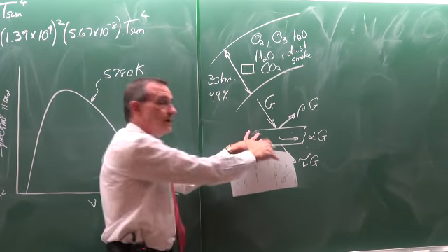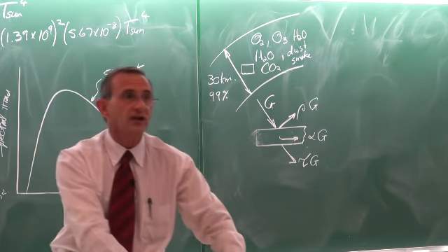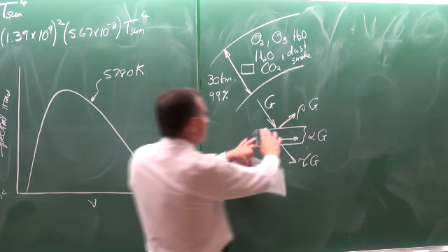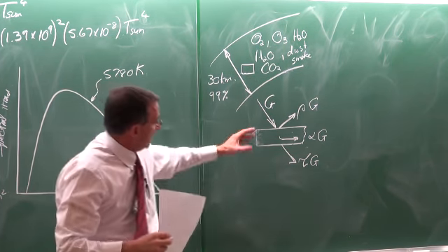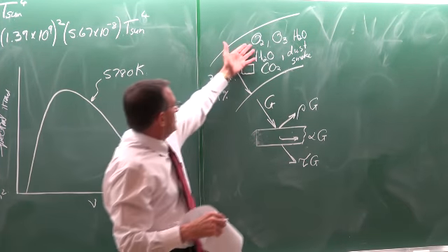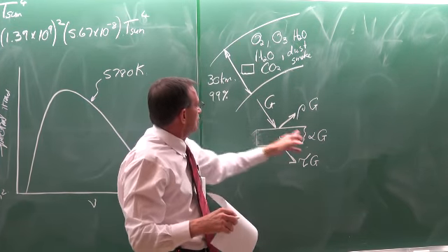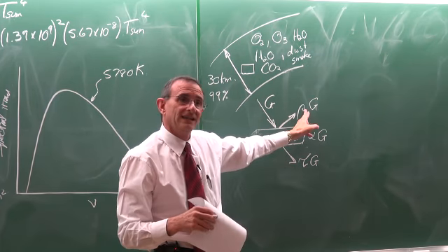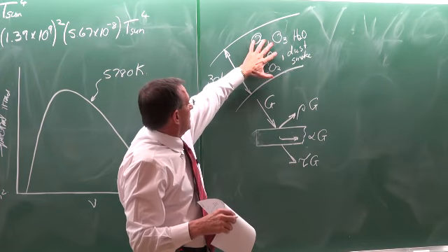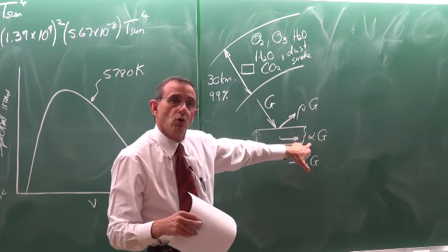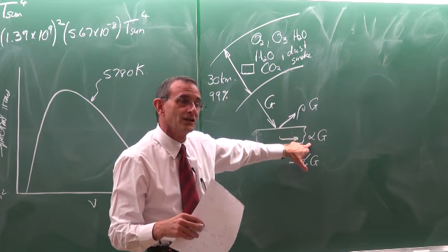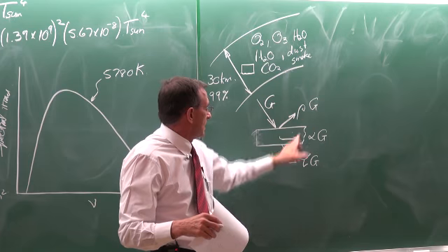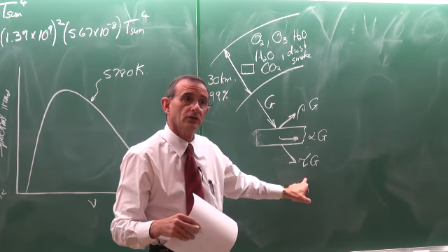Now this medium, very importantly, is not always something solid or glass. A gas does the same. So for any of these gases, a part of the radiation will be absorbed, a part would go right through, and a part would be reflected. Now, in general, the alpha is very small, so little is absorbed. But much of it is reflected, and most of it would actually go right through.